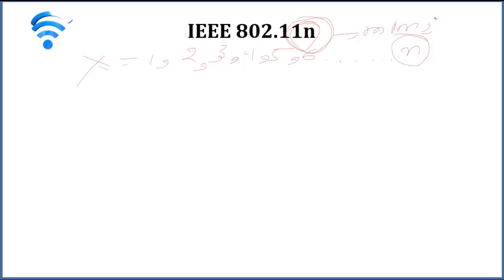So the first requirement is to support an OFDM implementation that improves upon that employed by the 802.11a and 802.11g standards, using a higher maximum code rate. Doubling the number of spatial streams from 1 to 2 effectively doubles the raw data rate. So there is a trade-off, however: increased power consumption and, to a lower extent, cost.